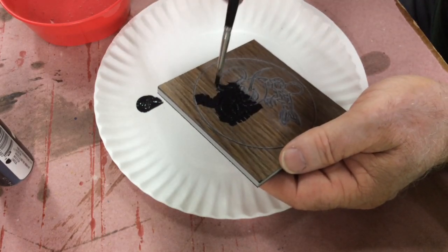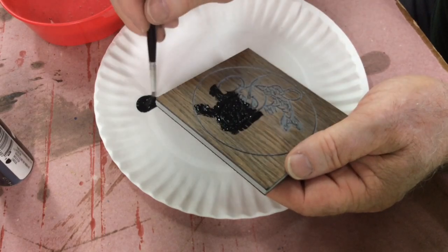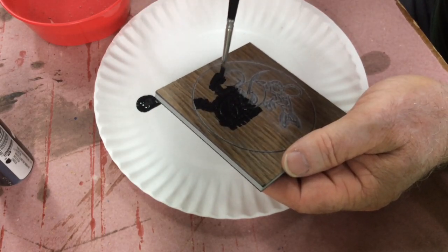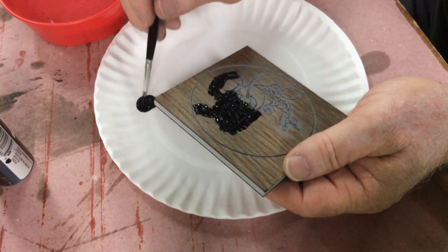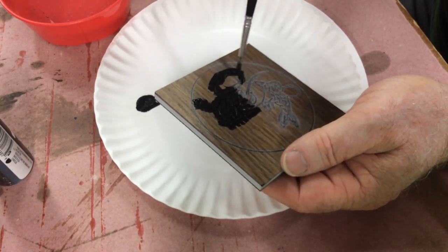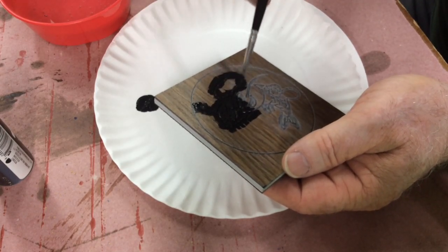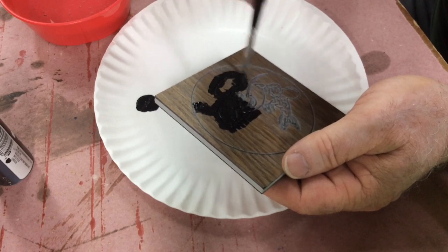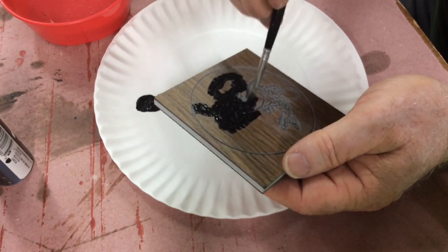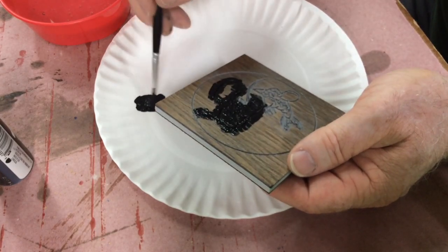And I used the cut depth instead of 0.04, I went ahead and cut it at 0.03. And then I came back with a finishing cut where I dropped the finish down to the 0.04. And that gave a very nice finish. Like you saw, the only thing that I really had to do was just touch it up with a toothbrush, and it cleaned it up nicely.